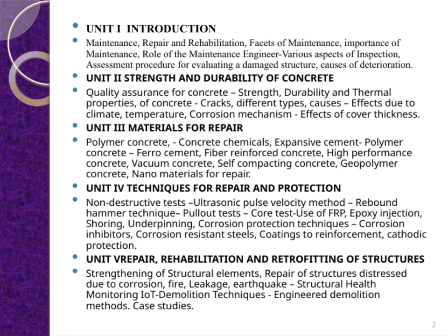The fourth unit covers techniques for repair and protection. We'll review non-destructive testing methods such as ultrasonic pulse velocity, rebound hammer, pull-out, and core tests. We'll also examine advanced repair techniques involving FRP, epoxy injections, shoring, underpinning, and corrosion protection methods like inhibitors, resistant steels, coatings, and cathodic protection. Finally, in the fifth unit, we focus on repair, rehabilitation, and retrofitting of structures.